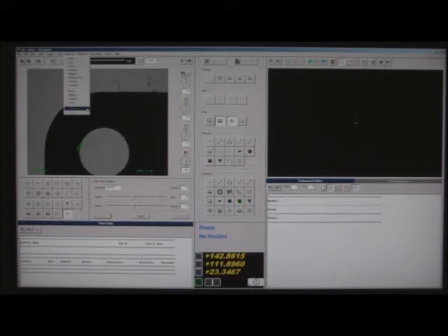What the digital I/O lets us do is control the machine, control an external apparatus on the machine. I could control a PLC that had an automatic loader-unloader for the machine, so that if we were loading the machine automatically with parts, the digital I/O could tell the PLC when the machine was in a clear position, when the inspection was complete, when it was time to load or unload the machine.